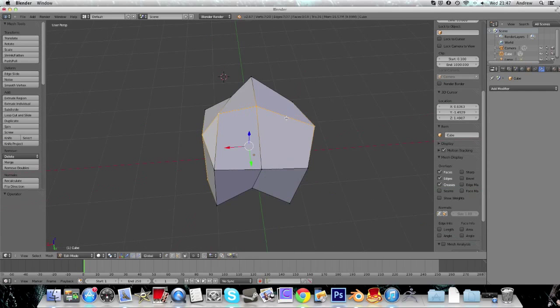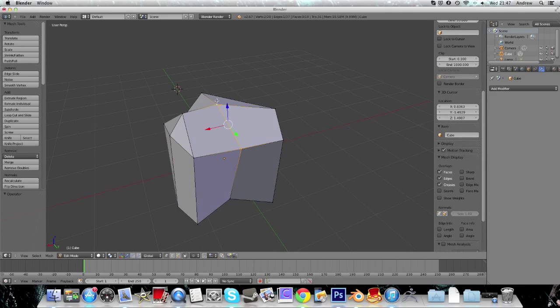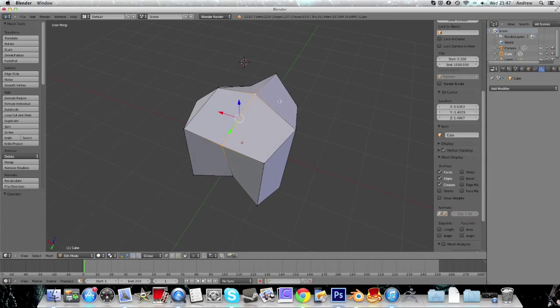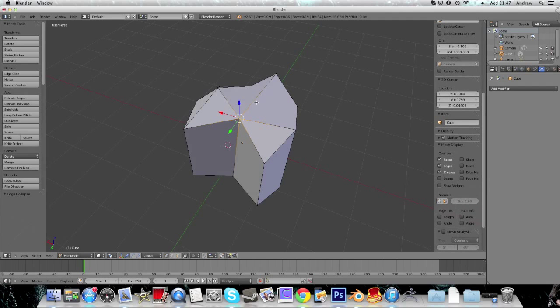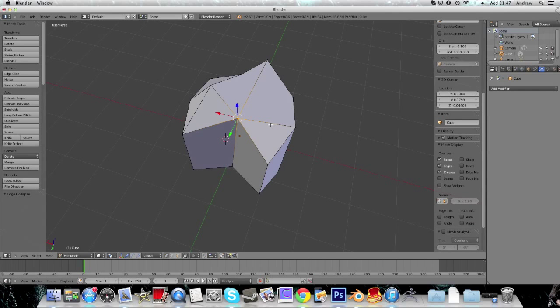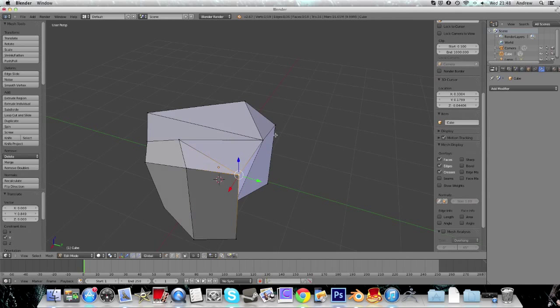But I'm going to keep this shape like this because I also want to look at how to edge dissolve or edge collapse. It's kind of like merging, so if I merge it at the center, it's going to give the same effect, but it's a lot quicker just to press those two and edge collapse, which connects them into one vertex, and then maybe pull it back. It's a lot easier than merging, because you've got a few more buttons to press to merge. So we can do that too, and that'll save us some modelling time as well as getting some cool shapes.